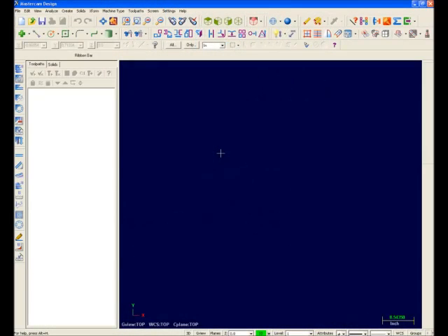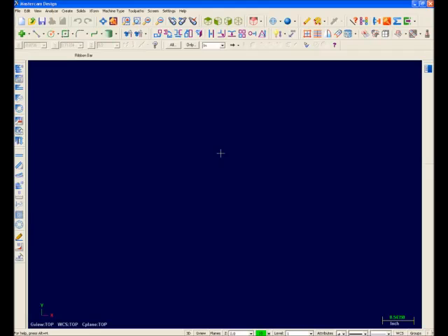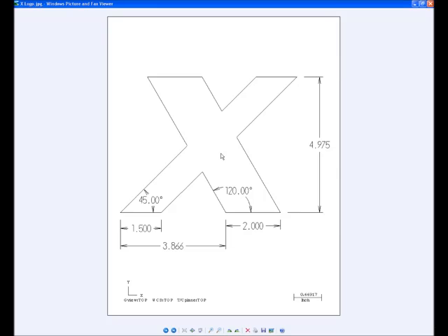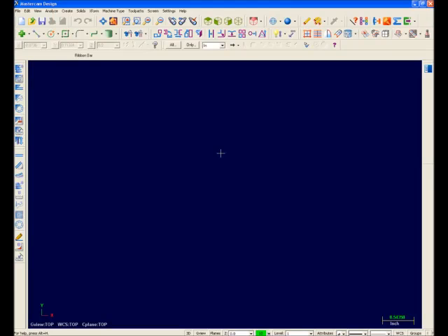Moving on, I'll talk about some basic wireframe development in Mastercam X. I'll just go ahead and turn off the Operations Manager by hitting Alt-O to give us some additional workspace while designing. Here's the print that we'll be drawing from. Let's begin by drawing the 1.5-inch line at the bottom. Before we start, I'll select Alt F9. This displays my tool plane, construction plane, WCS orientation, and origin location. To begin, I'll select Create Line Endpoint. As you can see, our ribbon bar is now available.